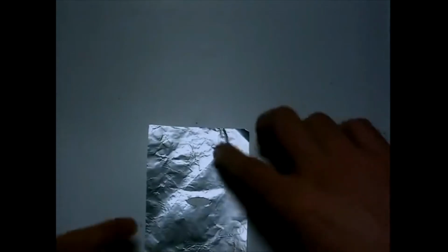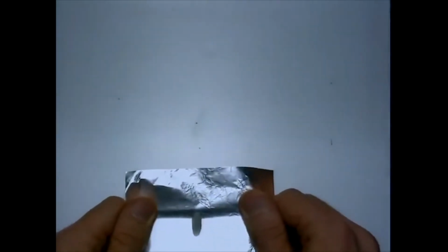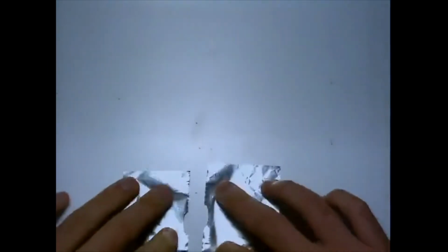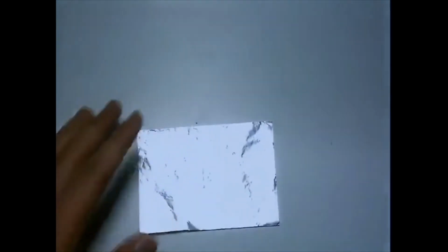Okay, come and do another one. I actually made this hole. Do it that way, but be careful. Slowly. You can see the blunting of the hole at the crack tip, and eventually it starts to break. Aluminium is supposed to be very plastic, but in this case it still looks very brittle. Go ahead.